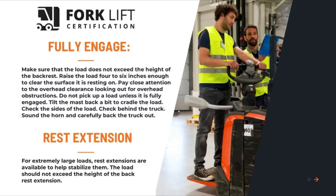Tilt the mast back a bit to cradle the load. Check the sides of the load. Check behind the truck. Sound the horn and carefully back the truck out.